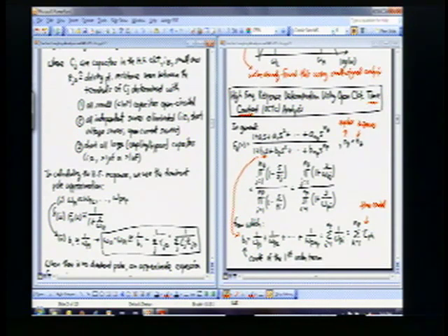Because if we can assume that we have a dominant pole, then you have an omega p1, you have an omega p2, and all the way up to omega p np, where again np stands for the number of poles. That's the total number of poles. But if omega p1 is much less than all of those other poles, then from this equation right here for b1, I can neglect all of these. Because if they're much larger than omega p1, they contribute such small terms compared to omega p1 that they just don't matter.